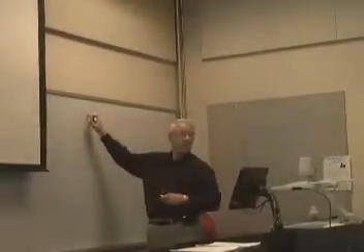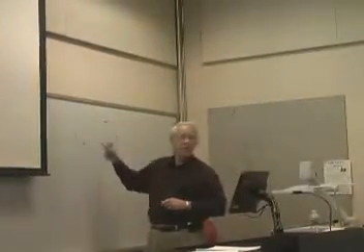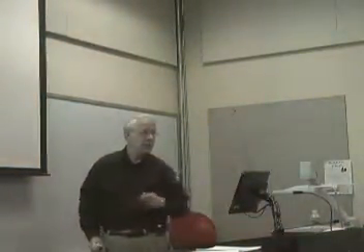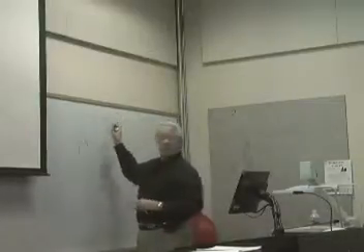So how many total nodes do I have? These are called, now, globally, how many nodes? 3. Right? So I'm going to have a 3 by 3 matrix that I have to solve for the unknowns T1, T2, and T3. But I've done what we call assembly. That is, I've done the operation on an element by element technique. And so it makes it very, very quick to do it at that level.